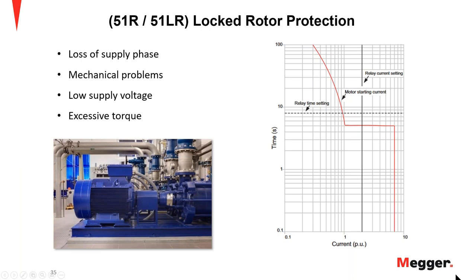So during startup, as expected, there will be a large current draw from the supply, and this will cause extremely high temps inside the motor. But until the motor gets up to speed and has begun to move, that's when it'll improve its cooling, because the fan that's internal to the motor needs to be moving.